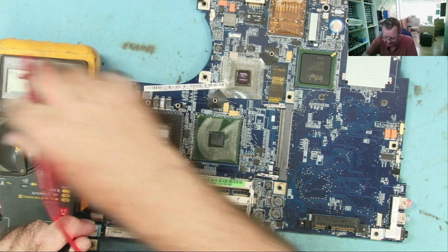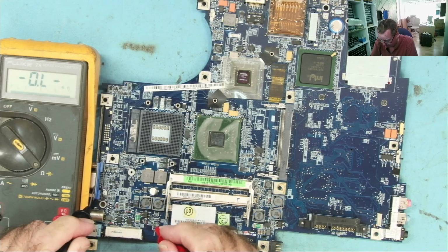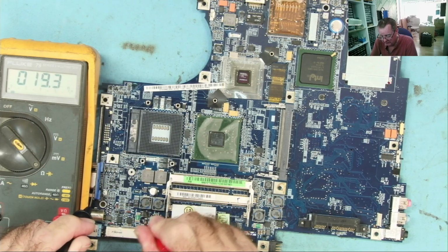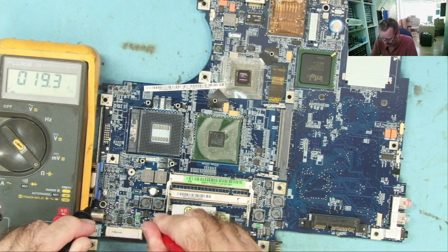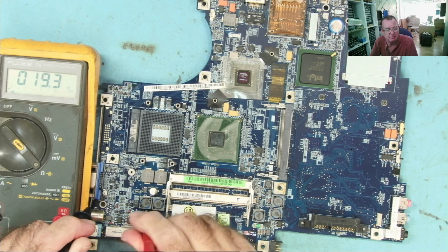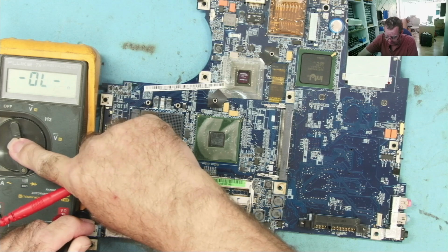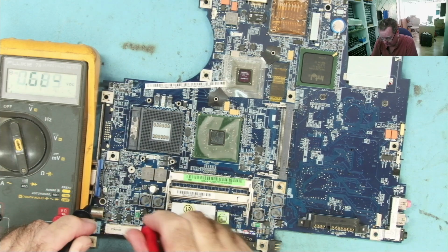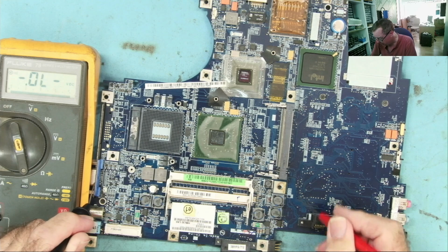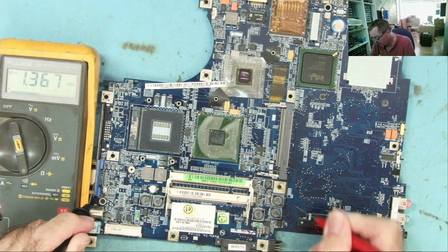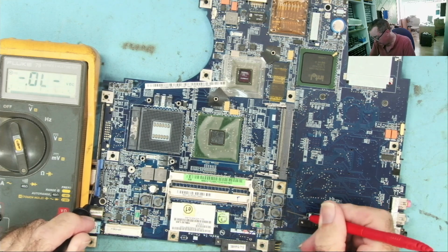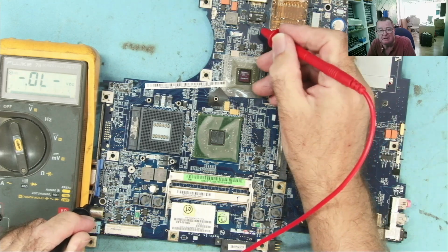Yeah. What did this tell us? Like a Schottky diode, it's 160 ohms. This one, 19 ohms. Okay, so that's not a short, that's a resistance of a load. Diode mode looks like a short, and we had one over here even lower. In fact, no, it was up here even lower. This one.